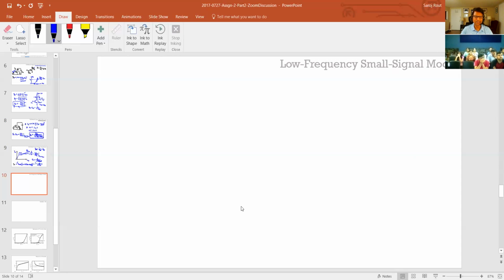So sub-picohenries in these kind of feature sizes, they're pretty much inconsequential. So that's why we never talk about inductors inside, unless you want to build inductors. So there are ways to build inductors, but otherwise not. So your biggest parasitic component is your capacitor, right?